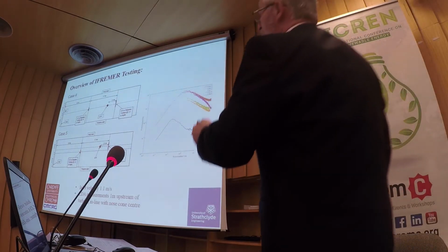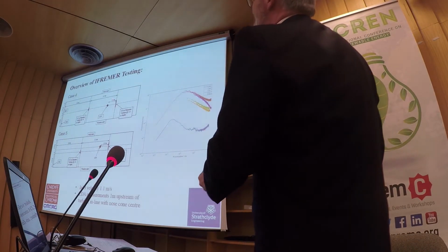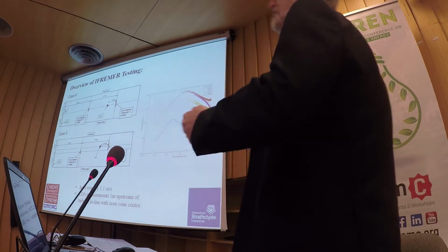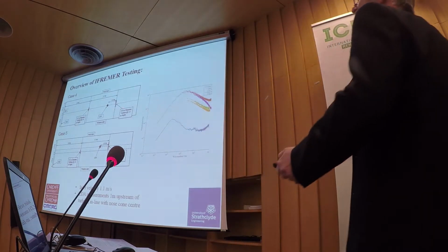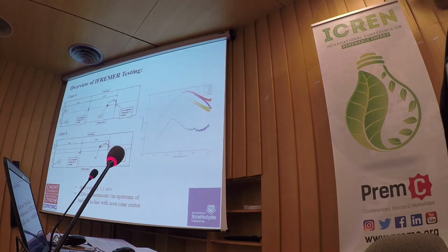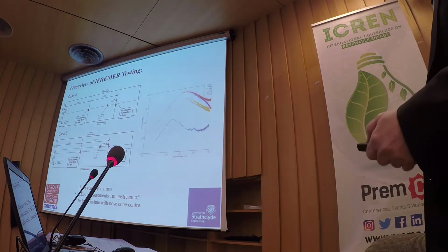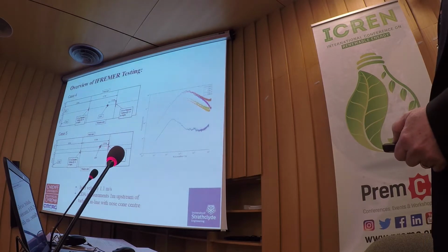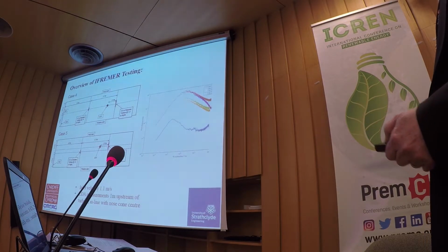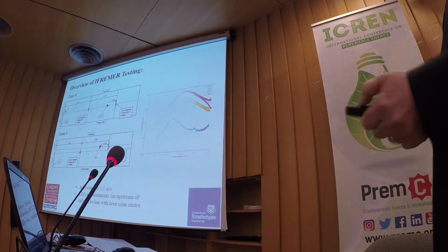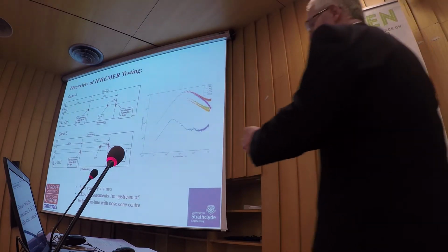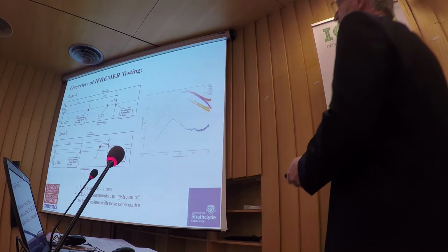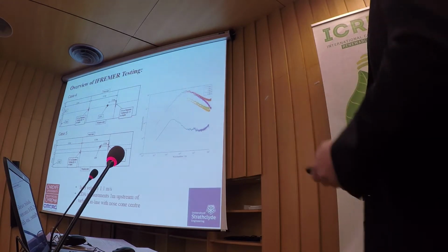The interesting outcome of this, when the turbine's directly behind another one, because you have a deficit, the actual amount of power out and thrust is down. The average stays about the same, but your fluctuations in load and power are high. Hence, you don't really want it hitting or in contact with the downstream turbine.